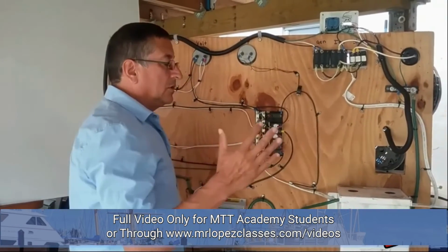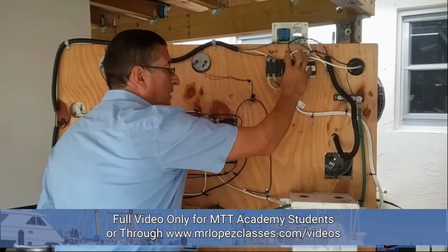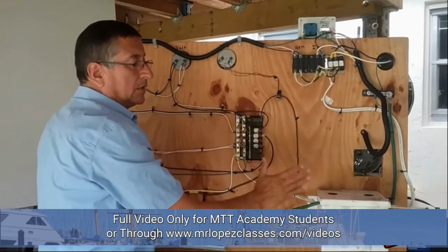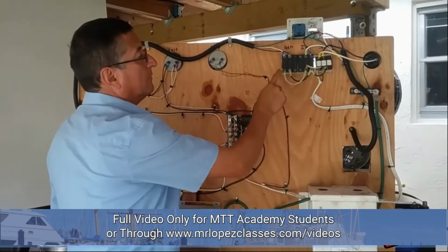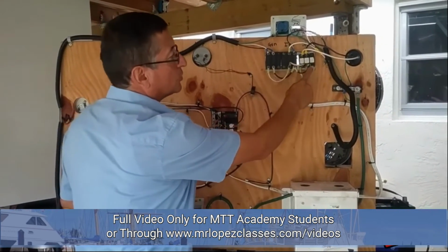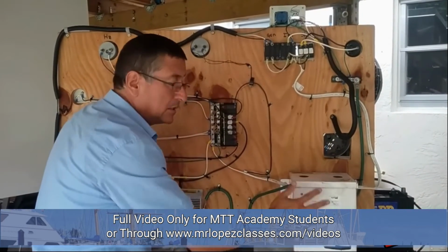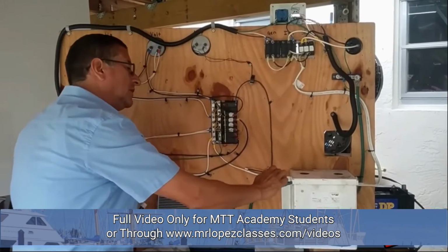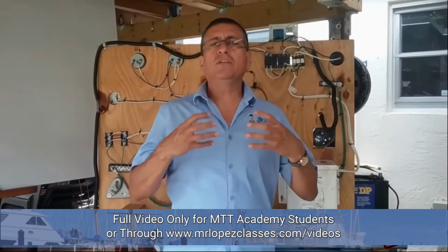According with my recommendation, the isolated transformer should be located in between the switch selector and the main panel. Why? Because in this location, I clean the signal coming from generator, or coming from inverter, or coming from shore power. All of those 3 signals are cleaned, and the signal will be completely clean in the output of the isolated transformer.